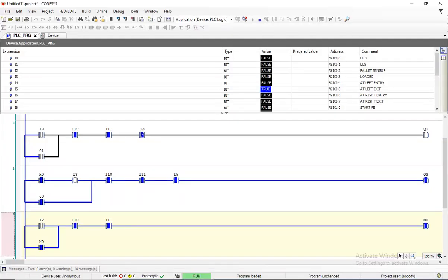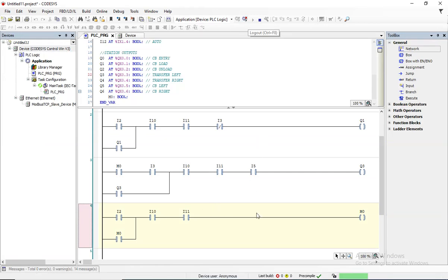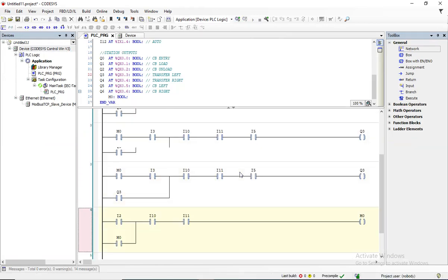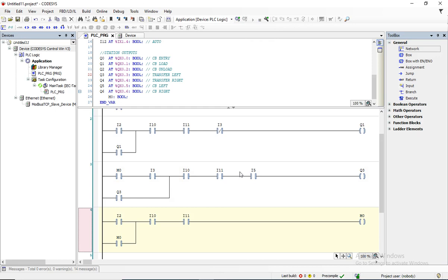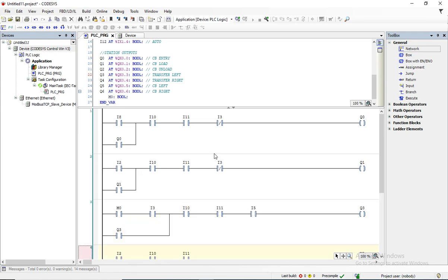We'll see. Let's then make a plan. So we now see that the Q3 is still running, right? That's not a problem. So we are able to activate that. So another person would say, let's deactivate it with the sensor just next to it, and the whole program like this must activate the conveyor belt, which is Q5.